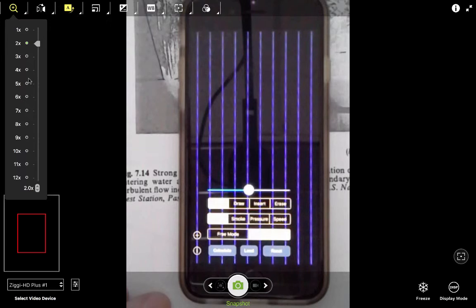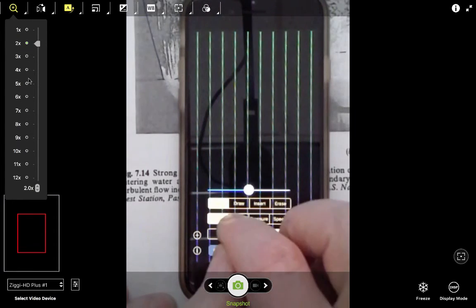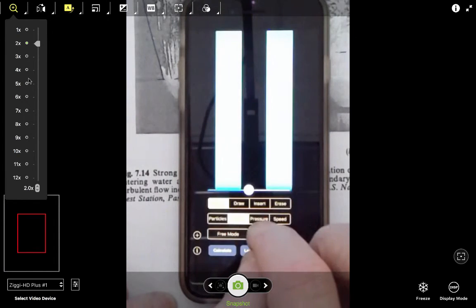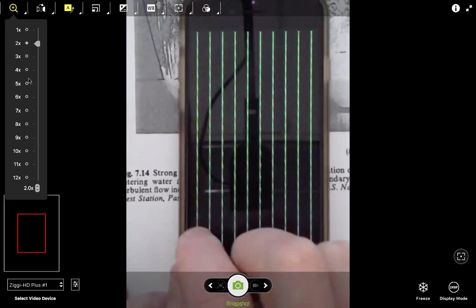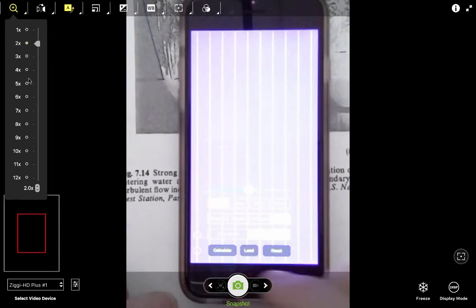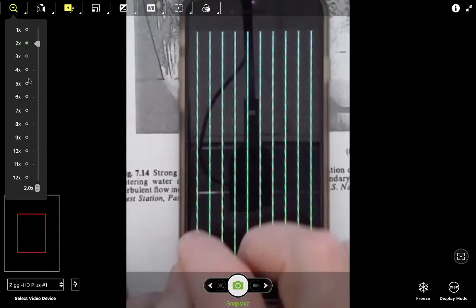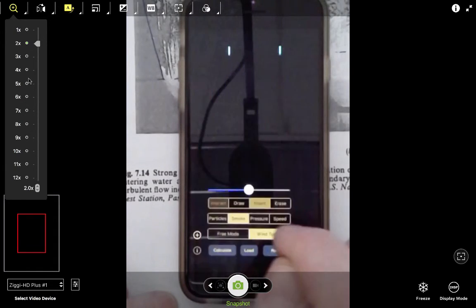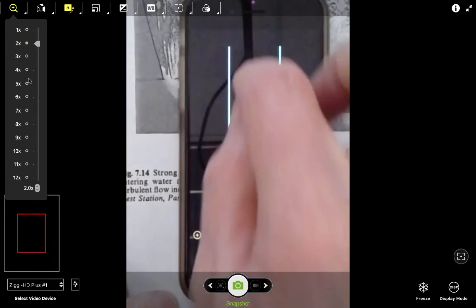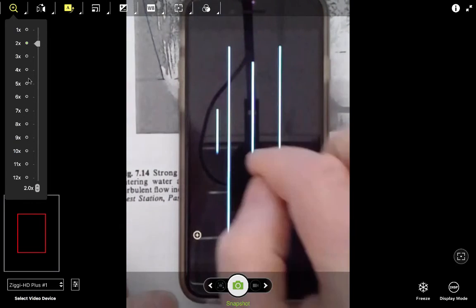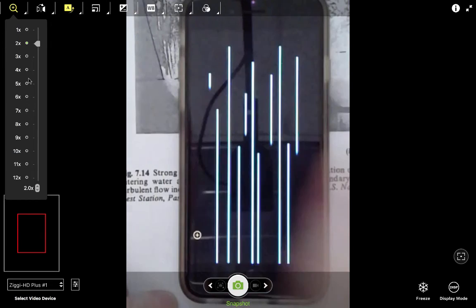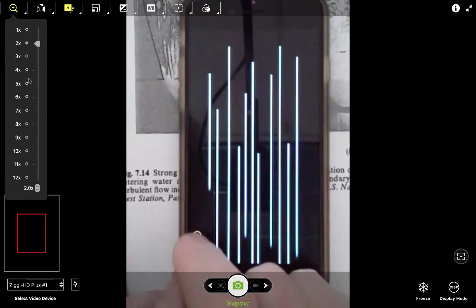And see, currently we have it doing particles. We can have it representing it as smoke traces. It isn't very interesting. It can draw a pressure field, speed. Let's go back to particles. And we can insert particles at different positions. And so now what we're producing are path lines.